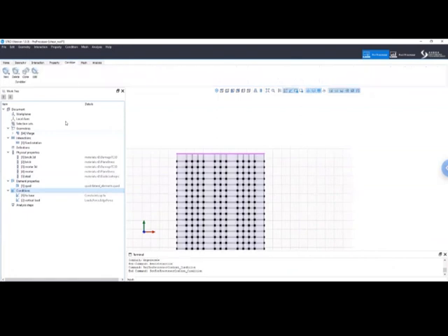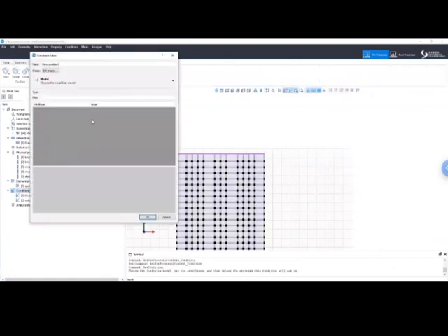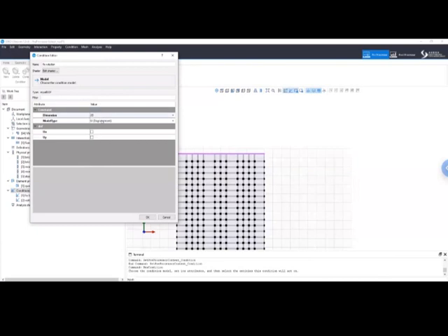So we can use this interaction to create the next boundary condition here. So we go under condition, and we create an add. Let's call it fixed rotation. We go under model. This time we choose constraint, multi-point constraint, because we want to constrain a slave degrees of freedom to a master degree of freedom. And we choose an equal DOF. We are in 2D, just displacement is fine, and we check both of them. Why? When we check the Y direction, basically this one will prevent the rotation of the top beam, because all the nodes of the top beam can displace in the vertical direction of the same amount.